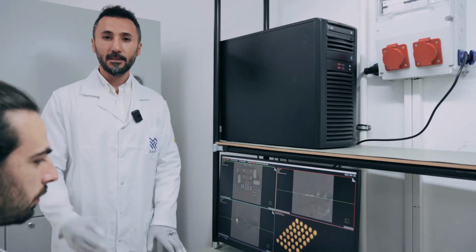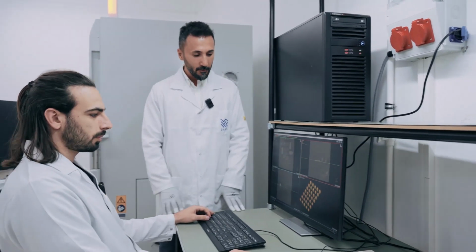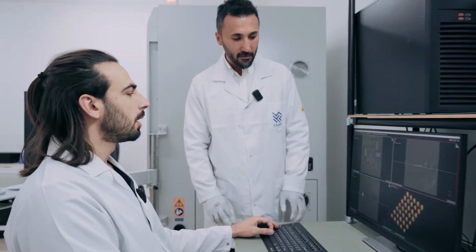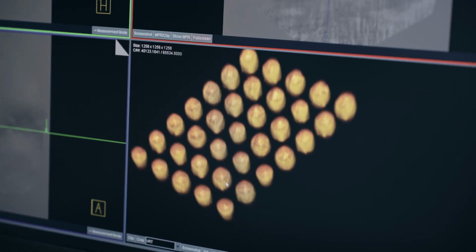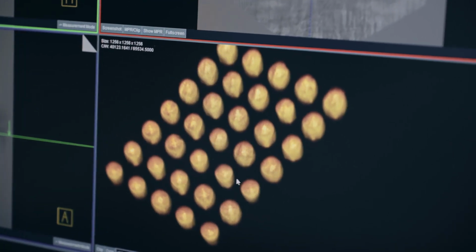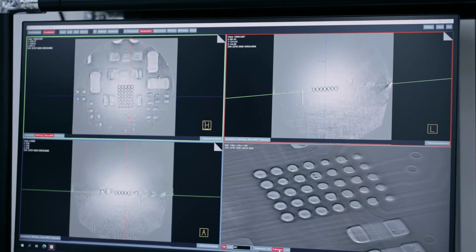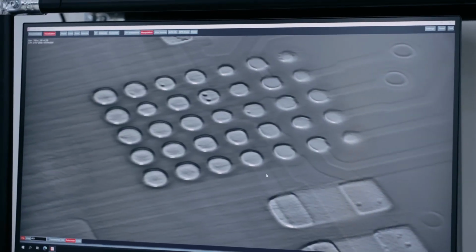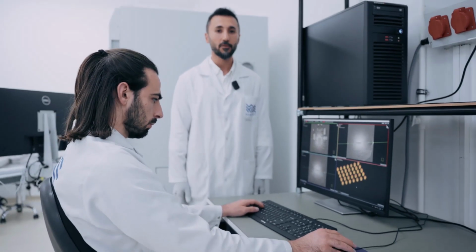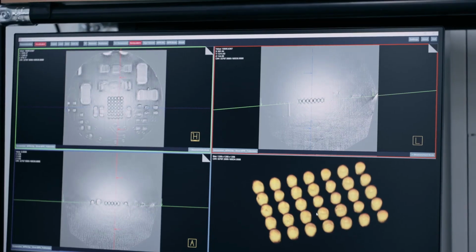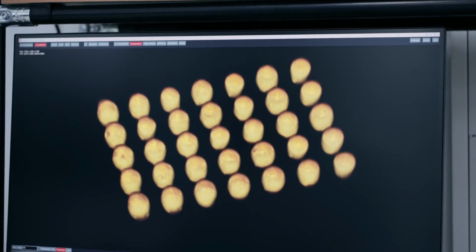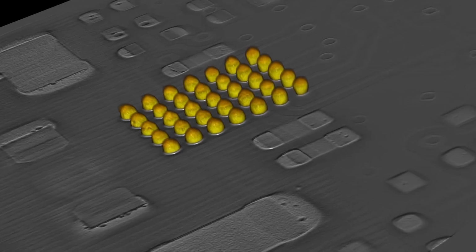Engineer Mr. Alperin is at the laminography table. What processes are we carrying out? Thank you, Mr. Engin. Right now, in the three-dimensional environment, we are checking parameters such as the shape of the solder, the amount of air inside the solder, and the solder joints. As Mr. Alperin explained, performing 3D image analysis is extremely important to prove the reliability of solder joints. With 3D image analysis, we can thoroughly analyze solder joints, contact surfaces, voids inside the solder, and mechanical cracks in detail. Thank you, Mr. Alperin.